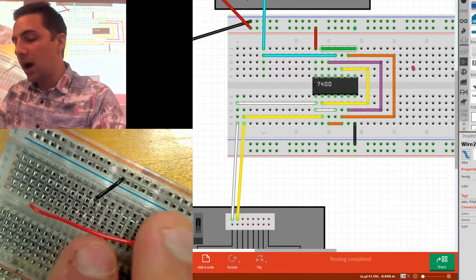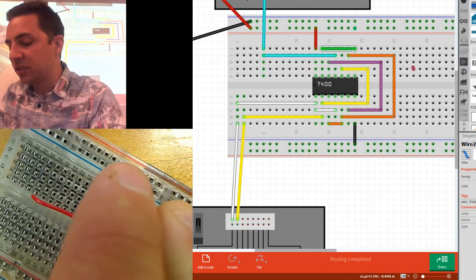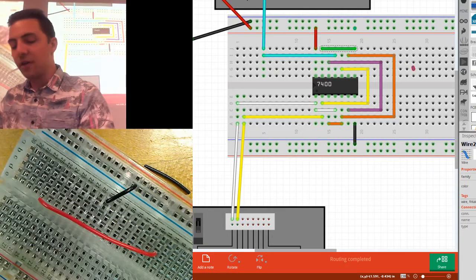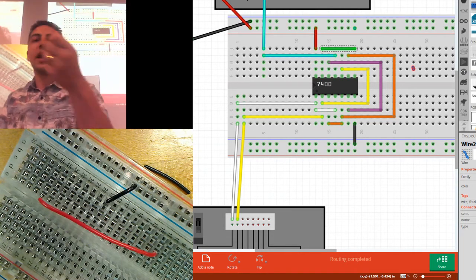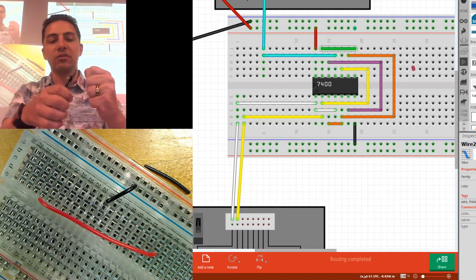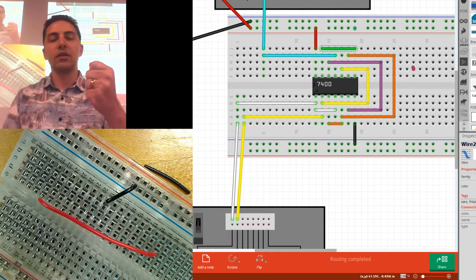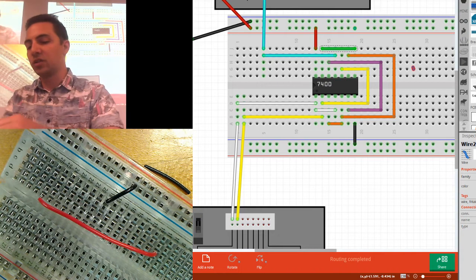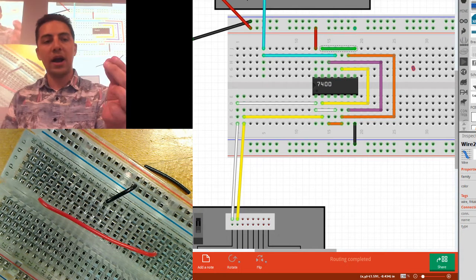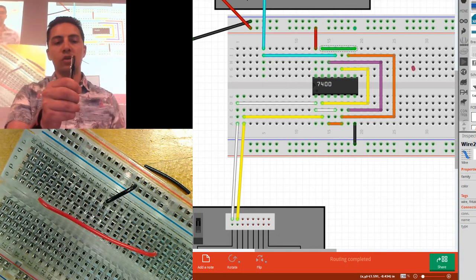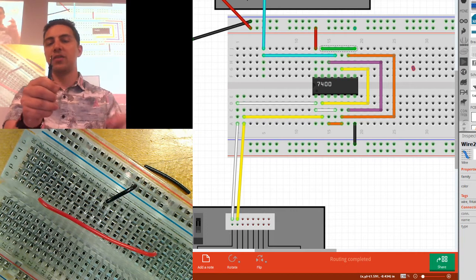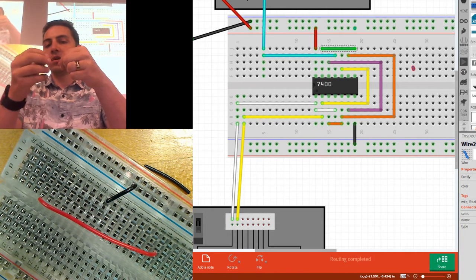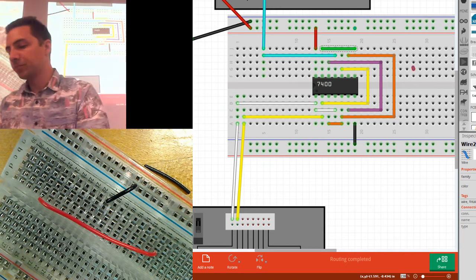Okay? So that's the two kinds of wires you're generally going to be cutting. These mid-range wires and these short wires. The first one is always easy because you've got a whole handful that you can hold on to, so you can just sit there and strip this all day. You know, you've got plenty of grip. But if you're holding on with two little fingers, it doesn't really work. So what you want to do for a short wire is grip it, turn it into a bit of a Z crank, give it a couple of spins, and then that insulation will come right off. Okay.